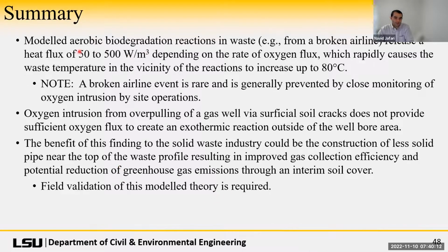For the modeling, what was important here is that as we get towards understanding initiation for ETLFs, we need to start quantifying the heat generation rates or fluxes. Aerobic is one that we started off with, and the flux is about 50 to 500 watts per meter cubed, and it's a function of how much oxygen is coming into the landfill. That will get temperatures up to 80 degrees C. But we also see that the heat generation is significantly variable. I think that's something we need to trend towards from our waste industry perspective: less temperature, more heat generation. Develop that sense of engineering judgment for that.